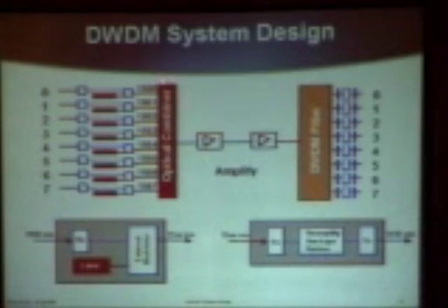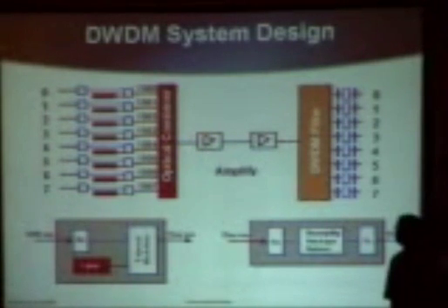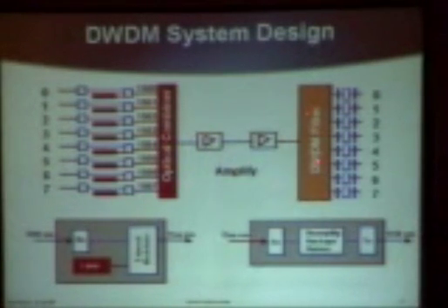So if I'd drawn this out properly, there is a set of channels that the ITU-T prescribes and everyone is standardized on. These are then combined, sent through up to, I think it's about 800 kilometers is the state of the art, using amplifiers approximately every 100 kilometers. And at the far end, you separate it back out using an optical filter that detects each wavelength and steers each wavelength to the right receiver.